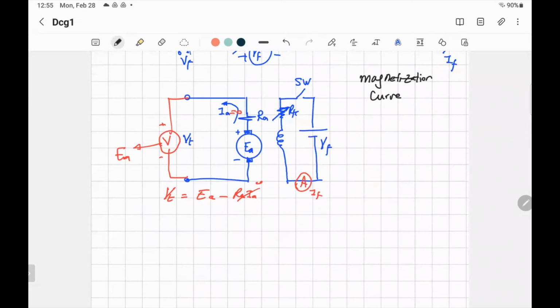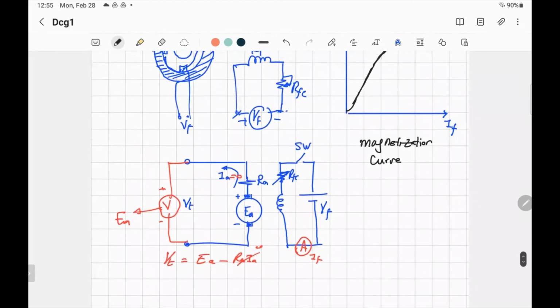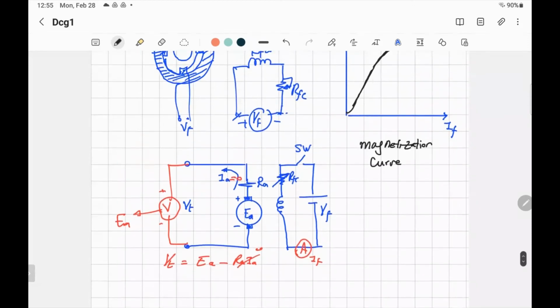With this careful calculation, are we going to get our voltage of 202 across the brushes, and are we going to get 200 volts across the load as we planned? Yes or no? Just give any answer. No. Why? Okay, that's one reason, because I did everything when IA was equal to 0, right?